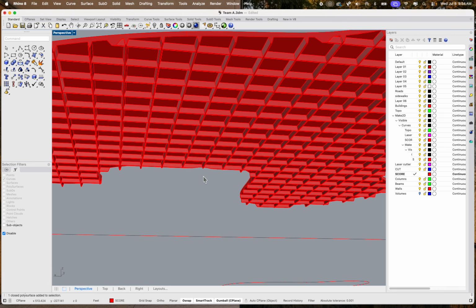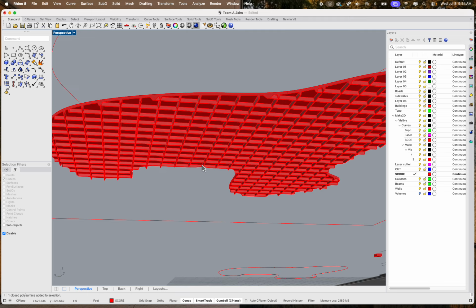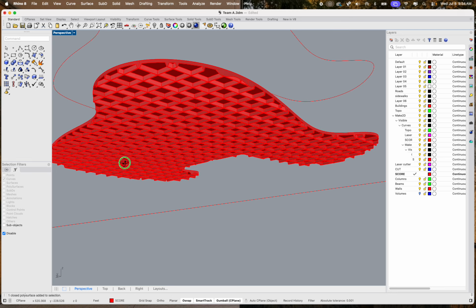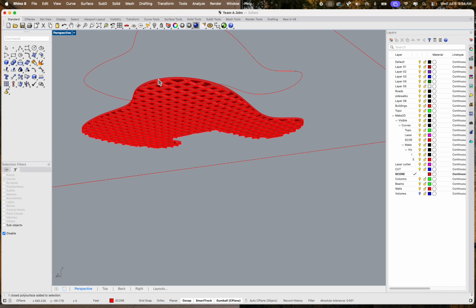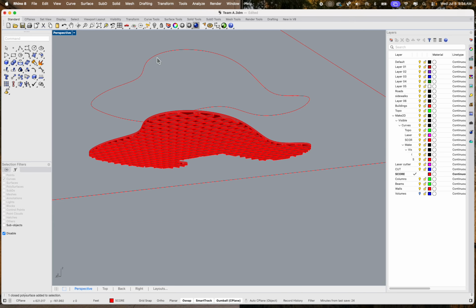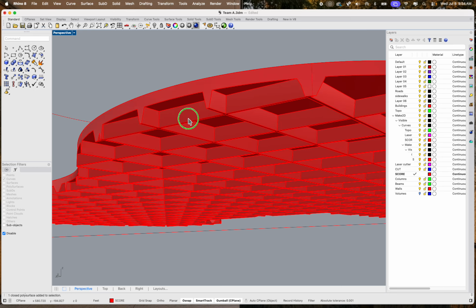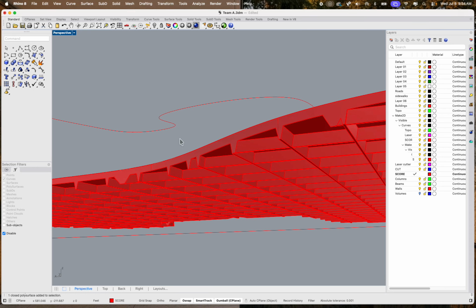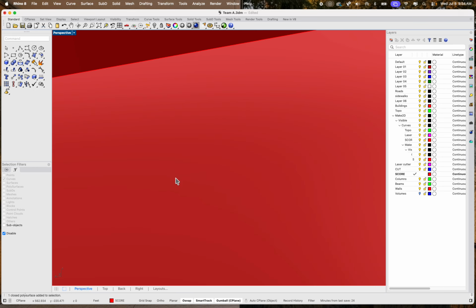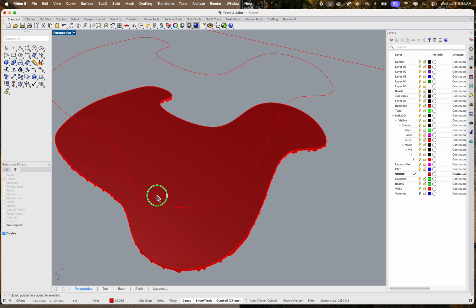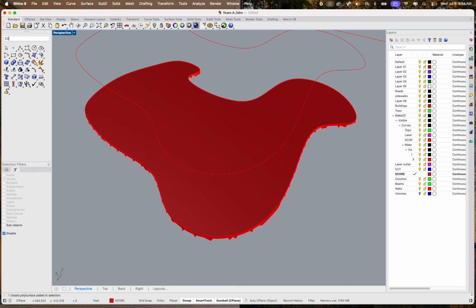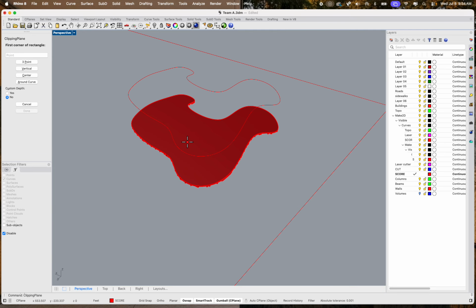And now that if I start making my design and starting to get a 1-point perspective or even outside in, we do something that starts to look arguably architectural. The next thing that we could do is give it some sort of frame, right? Some sort of boundary. So in my case, I'd probably want to match this profile. And if you can't get the profile, maybe this is the next thing that I really get into, the clipping plane. I know I've shown it before, but I probably haven't really shown its use yet.